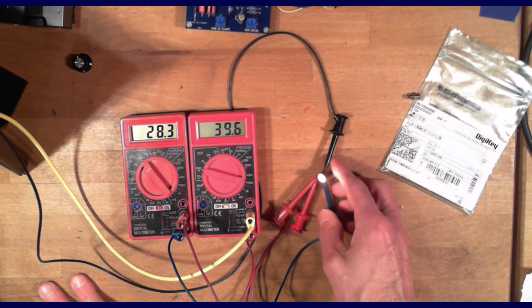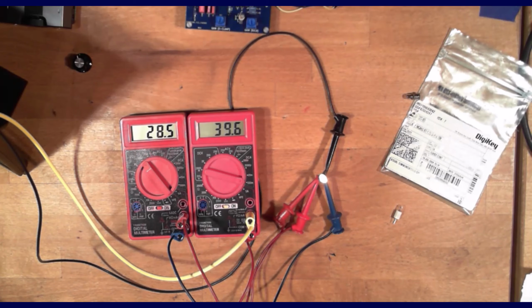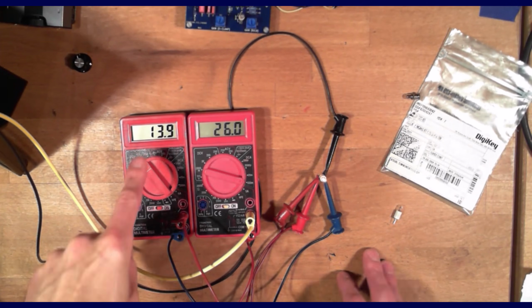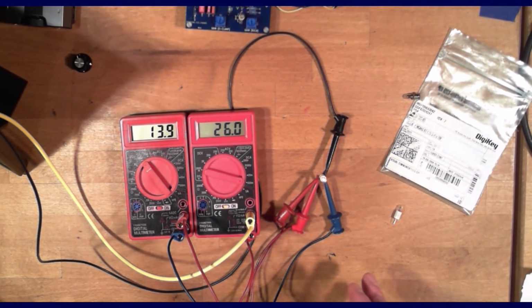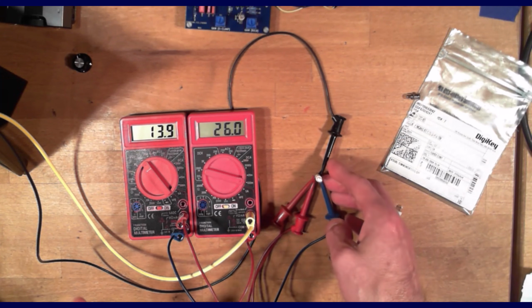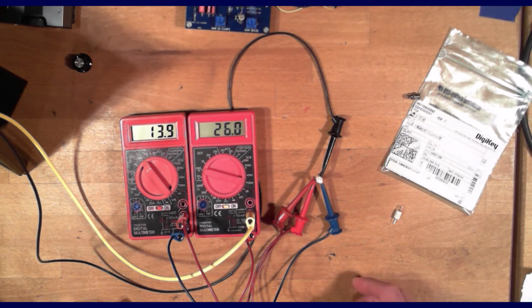Let's just do some mental math here. So I've got 28 and 40. Let me drop the voltage down to 14 and see if we get 20 milliamps. Okay, no, so at 14 we get 26 milliamps. So we actually have more current than we're expecting. More current means the resistance is lower. So as I increase the voltage across the light bulb, and increase the current, its resistance actually drops off.